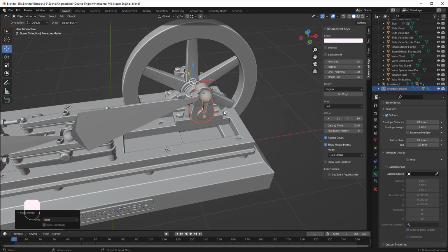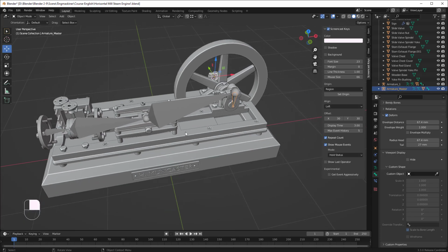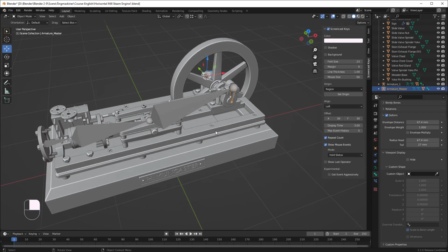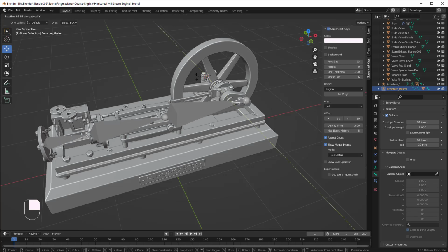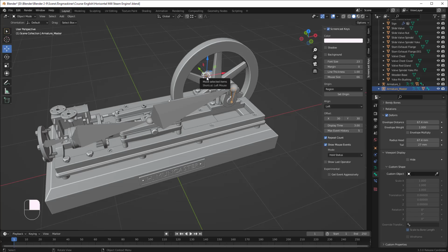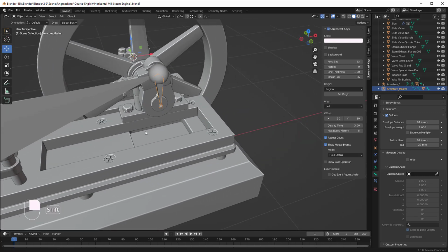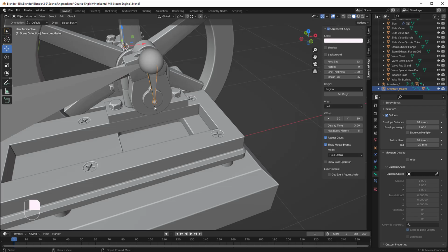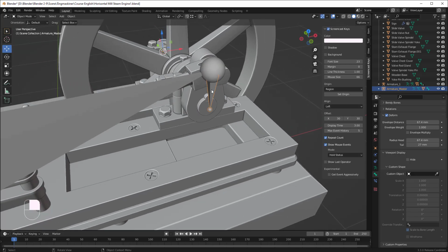That means now that if I select the master and then rotate, R and Y, around the Y-axis, we see that now the parts will move. But at the same time I see that the origin of the master is here on this side where the 3D cursor is, so I will move the origin so it will be placed here inside this joint.